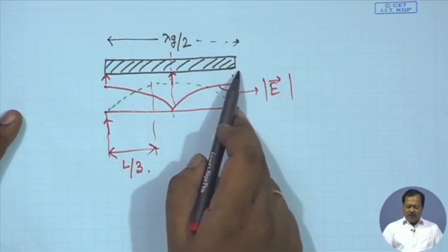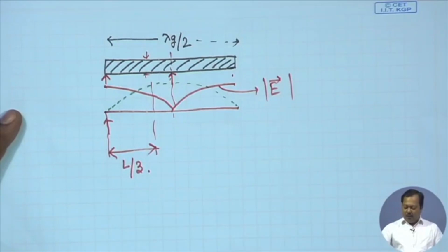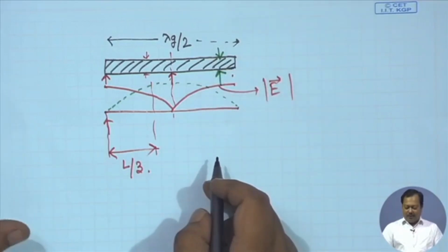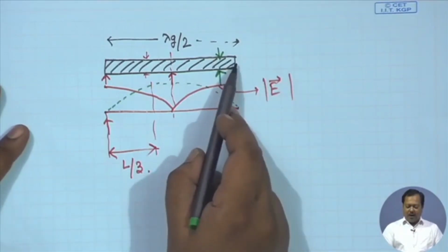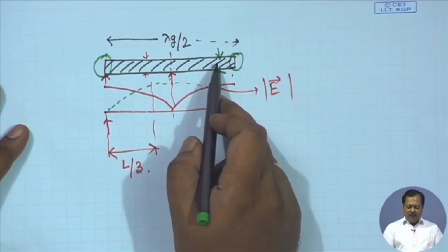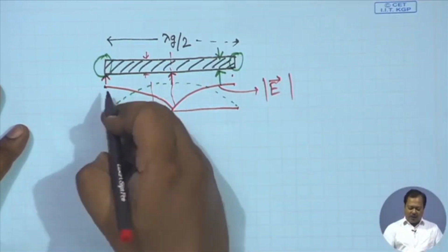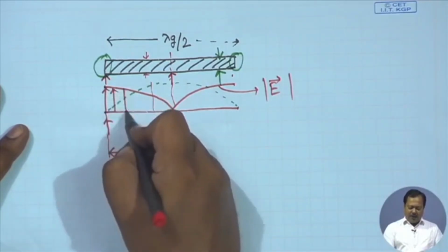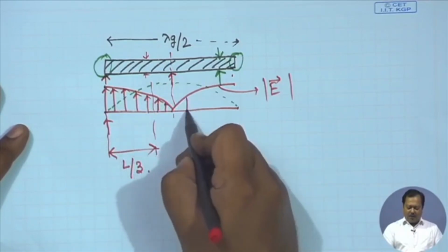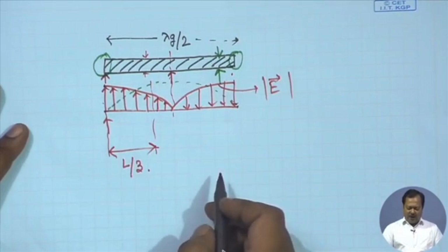This resonator, when its width is very small, will not radiate. But if we keep on increasing the width of the resonator, it starts radiating, and this radiation comes from the fringing field at these two sides. So, if I look at the fringing field plot, this is the direction of the electric field. I did not show it in this diagram. Since it is radiating, if it is upward on the left hand side, here it will be downwards, and at the end we have the fringing field.